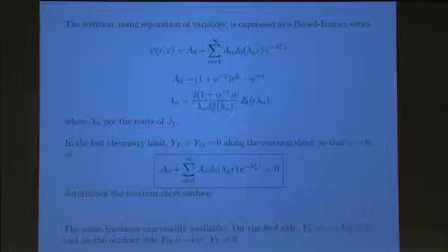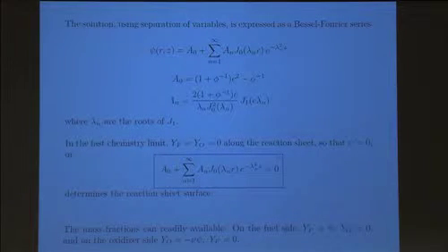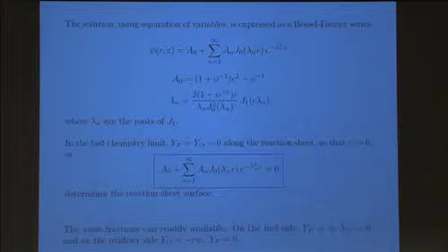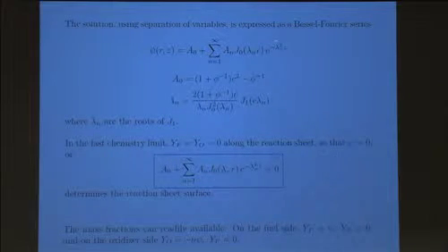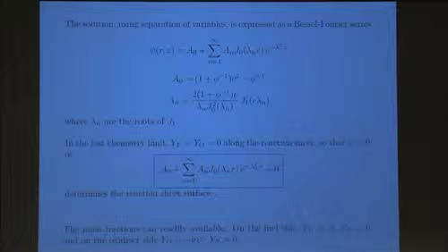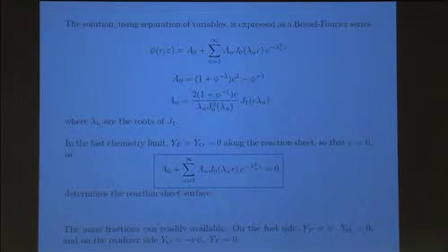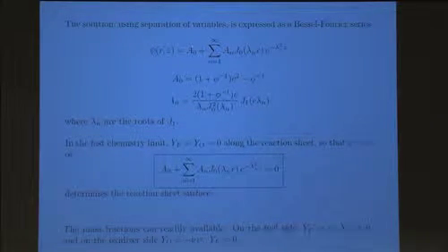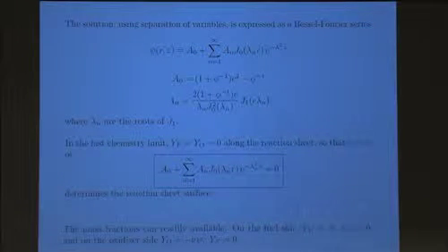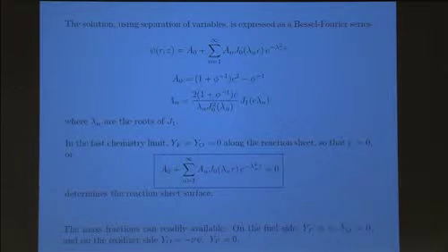And if you use separation of variables, then you obtain that the solution is expressed in this form. It's a decaying exponential in z in the axial direction, and this Bessel function in the radial direction. And the solution is an infinite sum, as you typically obtain in separation of variables. The coefficients A0 and AN are determined by satisfying all the boundary conditions. There is nothing particular in the details; that's just the form that you obtain.